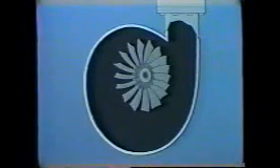Now let's review what we've seen about centrifugal compressors. A centrifugal compressor operates by the rotating action of an impeller to produce centrifugal force. This force compresses the refrigerant vapor to raise its pressure and temperature. There can be more than one impeller in the centrifugal compressor. If there are several, the vapor leaves the discharge port of one impeller and enters the intake port of the next one. Centrifugal compressors are large capacity units and operate at very high speeds.